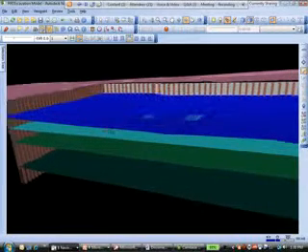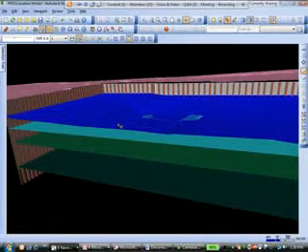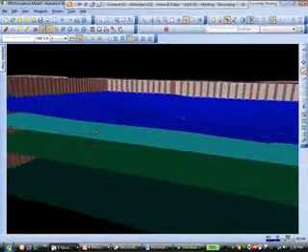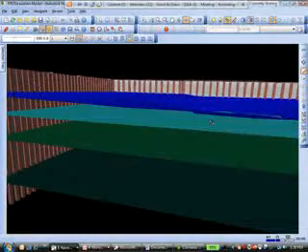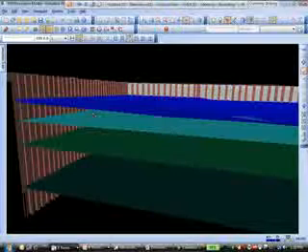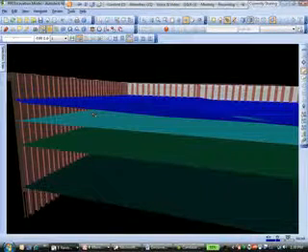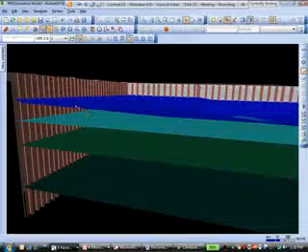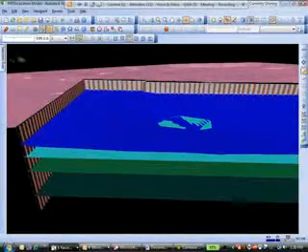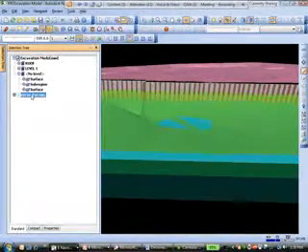And these become critical because now I can overlay the scanned surface and then determine if the contractor has achieved that goal. In this case, we can see that there's still a significant amount of dirt above that planned surface. So with this information, I could determine that, maybe on the pay application at the end of the month, I'm not going to award the full amount because there's a significant amount of excavation still left. We had a milestone that said you needed to be down to this particular level, but we're still a couple feet above that.